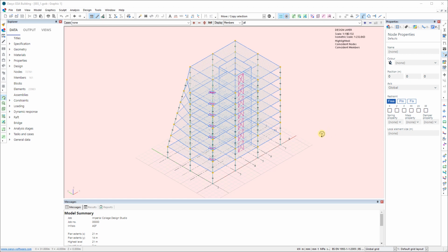So the first thing I'm going to do is, you see at the bottom, that's the grid that we defined, but it's only on this z equals 0 axis. But we want it really to be at the floor that we're extracting, which, as before, is the fourth floor. Knowing that each floor-to-floor height is 3 meters, we want to adjust that so we can also see it at 12 meters height, so the fourth floor level.